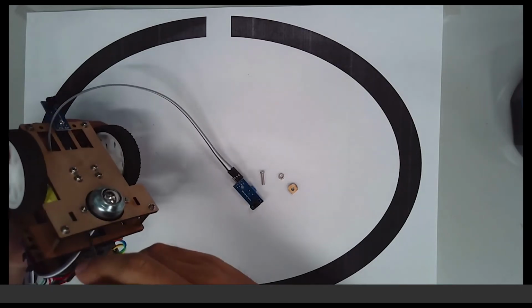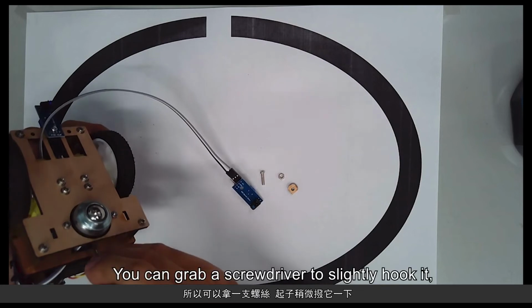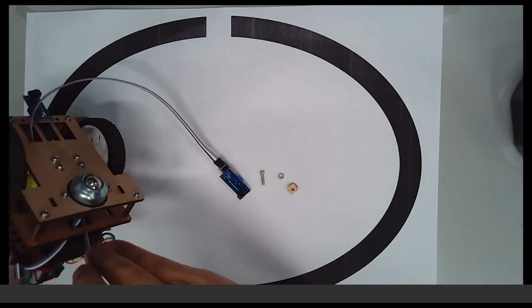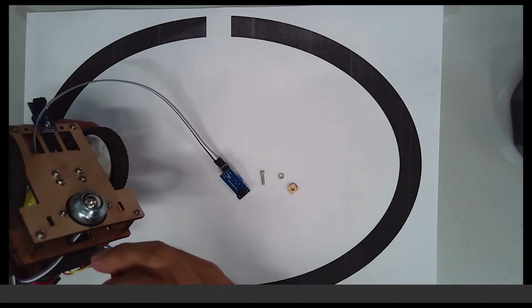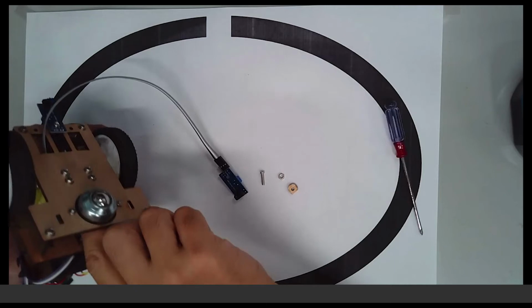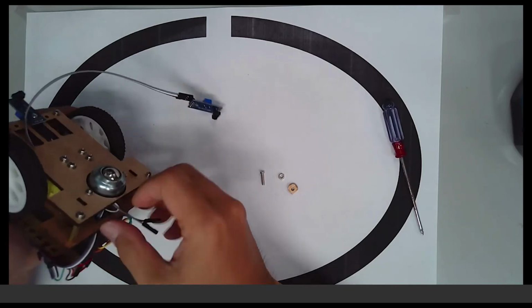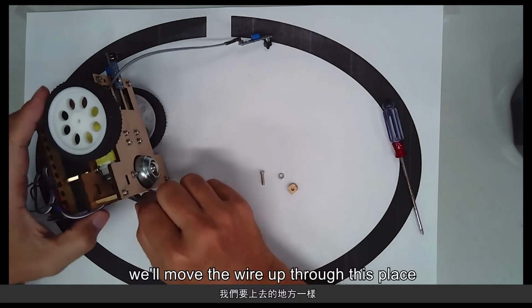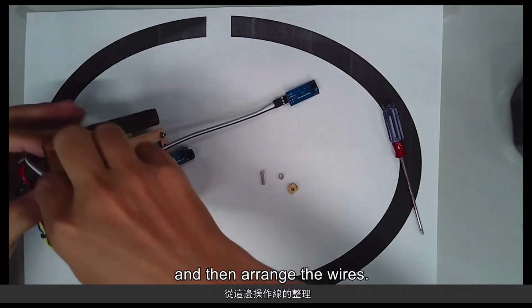It got stuck. You can grab a screwdriver to slightly hook it, but don't break any of the other wires, especially the wires of the motor that are inside. Pull this out. After pulling it out, we'll move the wire up through this place and then arrange the wires.